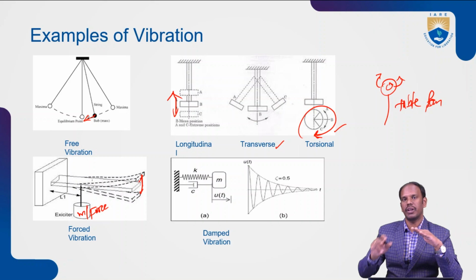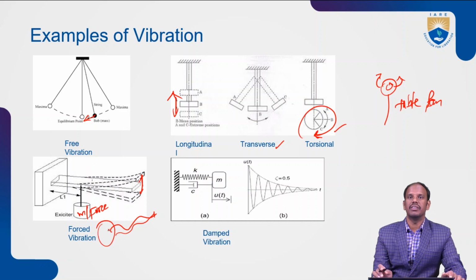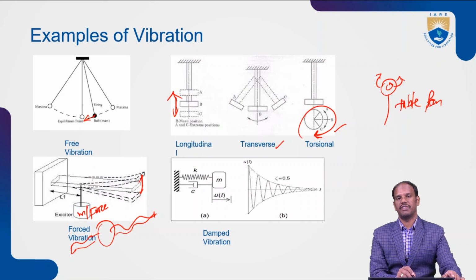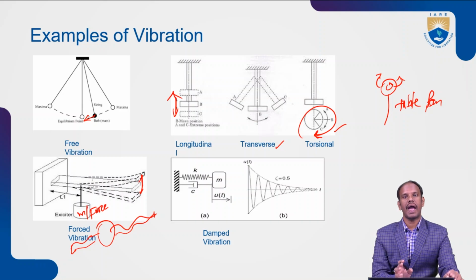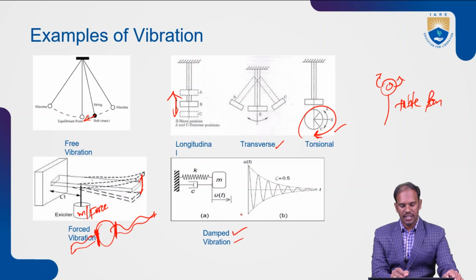Then there are physical models we need to reduce, like in the wings, where we have taken flexibility. The flexibility we have taken tries to move toward vibration-free, right? The vibration that happens is not transferred to the passengers' cabin. You may see a flutter happen to this aircraft also, but it does not cause any harm to the fuselage, because dampers have been attached towards the edges. Dampers have been attached towards the edges. They absorb all the energy and try to reduce the frequencies transferring to the fuselage body. And there are damped free vibrations. We say that there are damped vibrations.